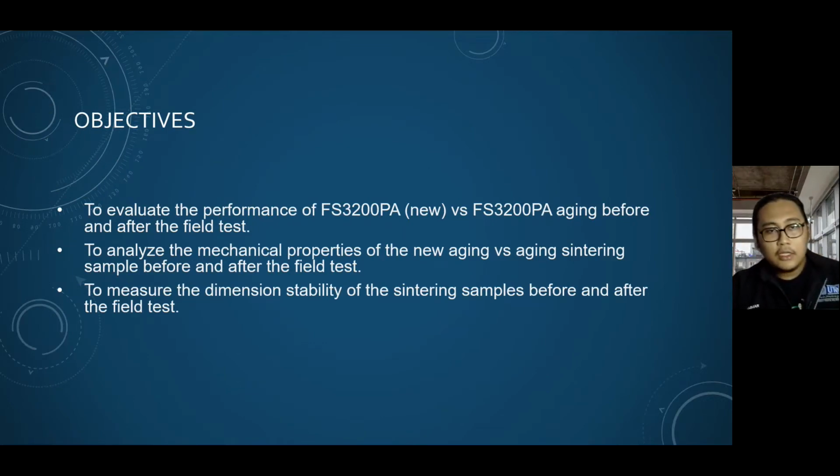My objectives of the study are to evaluate the performance of the new FS3200 PA versus aging FS3200 PA before and after the field test. Next is to analyze the mechanical properties of the new versus aging sintering sample before and after the field test. And to measure the dimensional stability of the sintering sample before and after the field test.